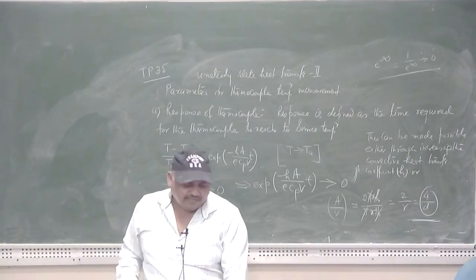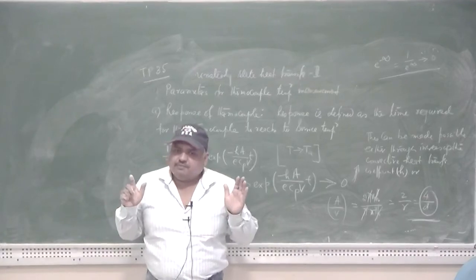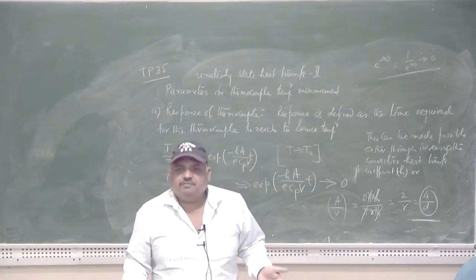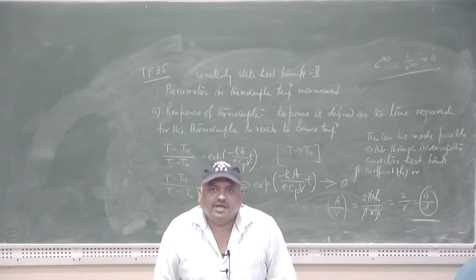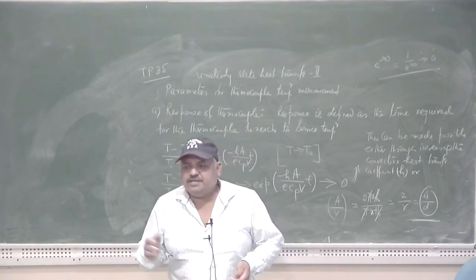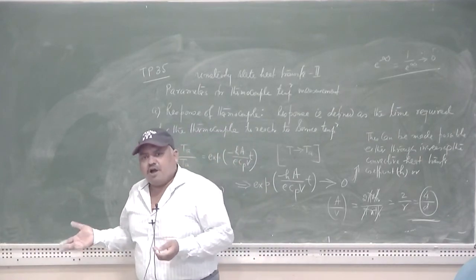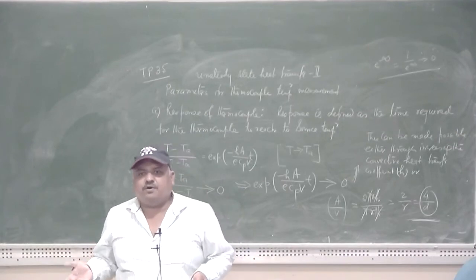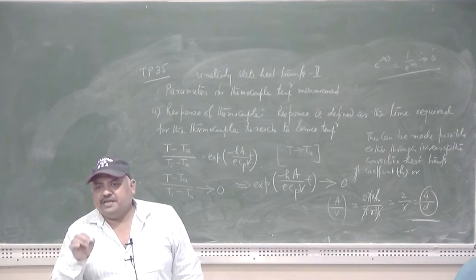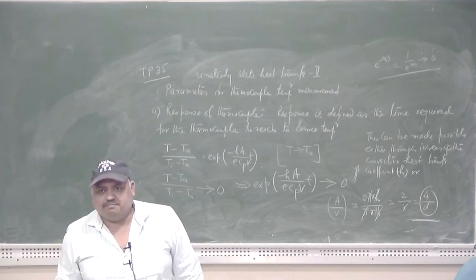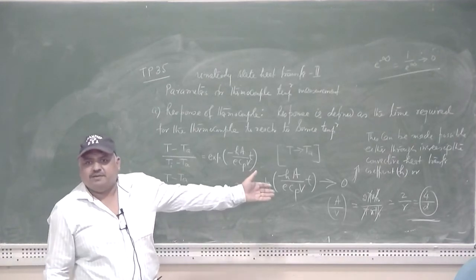This is the important design aspect of the thermocouple. The diameter of the thermocouple should be as small as possible. Henceforth, you can easily see that whether the metal combination is copper constantan, platinum rhodium, or iridium platinum, the diameter is kept at a bare minimum. Why? In order to improve the response time.